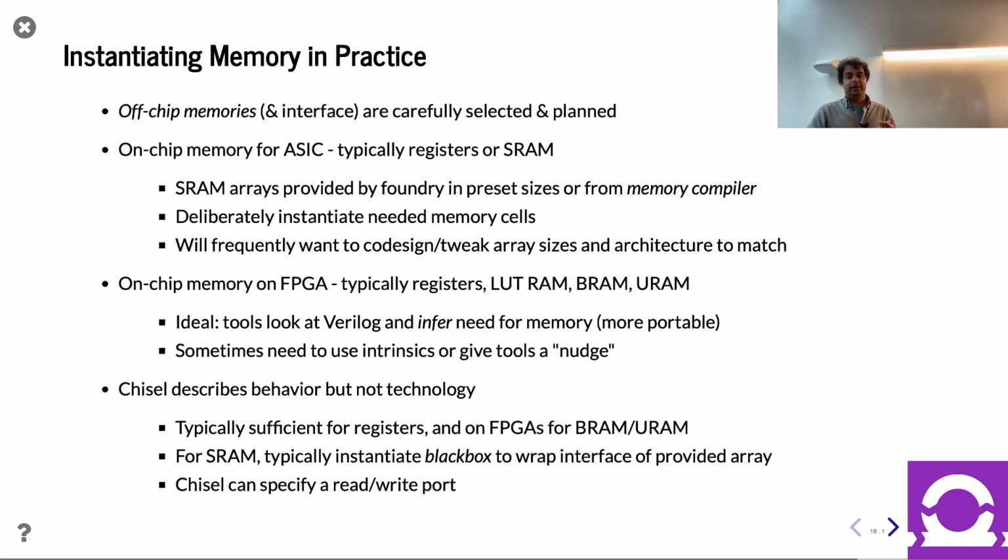So what's interesting is the FPGA tools, compared to the ASIC tools, are, I would say, a little bit safer, a little bit more robust. Part of the reason is they have less complexity to deal with, but they also have more end users. And because they have more end users, they can't always have support engineers there. There's more pressure in the calculus to make the tools actually work. So take an FPGA tool such as Vivado, hit some buttons. It's going to be closer to giving you a guaranteed design the first time than the ASIC tools were, by a large margin, right?